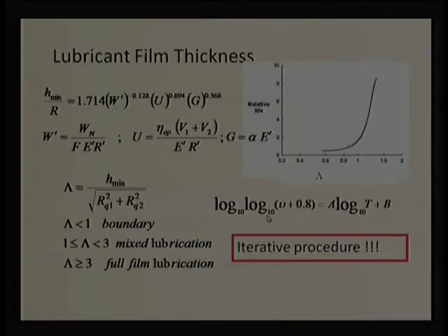Vogel's relation requires 3 constants, while Walther's relation, given here, requires only 2. When we see Walther's equation in a different book, sometimes we get this constant as 0.6, 0.7 or 0.8. But whenever we discuss gear oil, the kinematic viscosity in centistokes will be numbers like 30, 40, 50, 60, 70, 80, 90. So 80 plus 0.8 is not going to make much difference on a log-log scale. Of course, this is on a log-log scale.